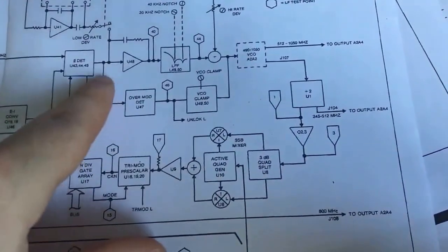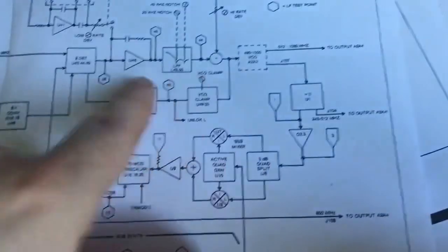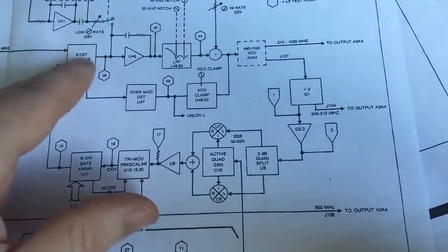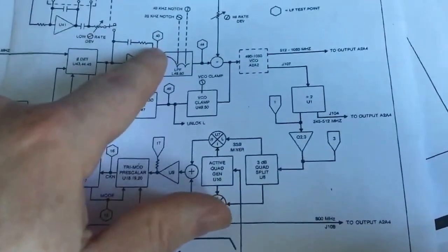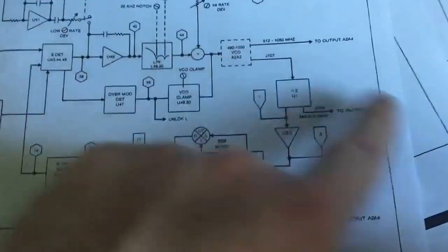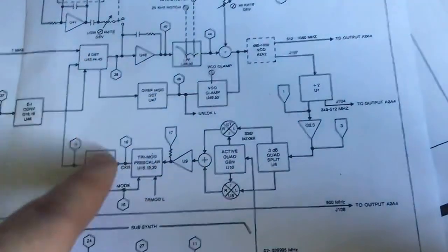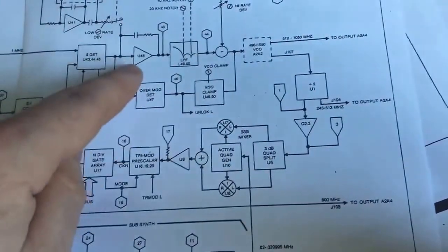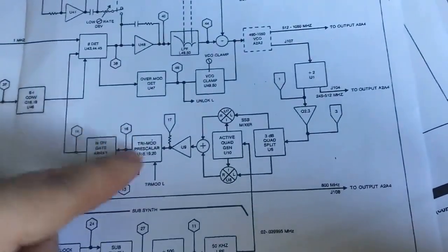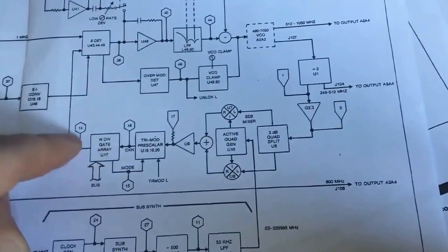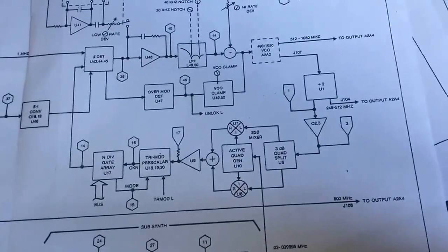And you saw me inject a voltage here before to manually control the VCO, and that will work fine. So was it just after there? Yeah, after that point, it's right there. Test point 40. So I injected the voltage there, and that controlled the VCO fine. So I know that from there outwards is okay. So it has to be before this point, and there's not much there. So yeah, I'm concerned. But I'm going to have to look at this and see if I can find a way of injecting a signal in here. A stable enough signal which is precise enough to work.